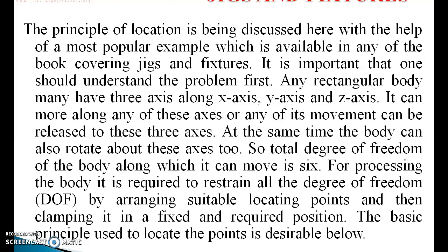For processing the body, it is required to restrict all the degrees of freedom, known as DOF, by arranging suitable locating points and then clamping it in a fixture at the required position. The basic principle used to locate the points is described below.